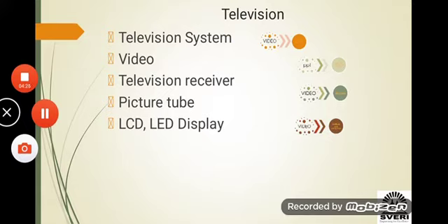What happens exactly at the display is that the electronic signal which has been converted by an antenna at the receiving side is processed and then given to a picture tube, where the picture tube is covered by the display screen, which is coated with a phosphor screen, so that whenever an electron beam strikes the phosphor, it illuminates.